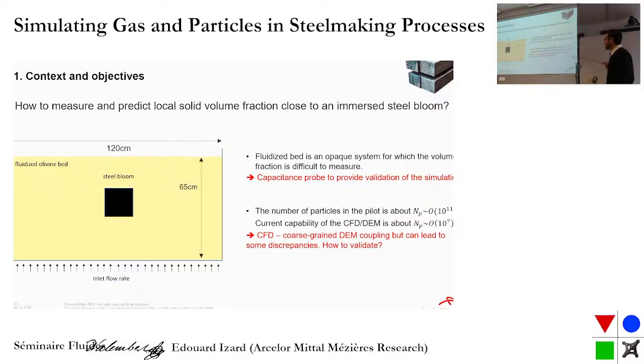Then the number of particles is quite challenging because you see it's 10 to the power 11 particles in this small bath. This bath is about 1 cubic meter, which is quite small in fact. But we have all of these particles inside this system, and currently the coupling between CFD and DEM that I will present later, with these very fine particles, it's almost impossible to simulate everything.